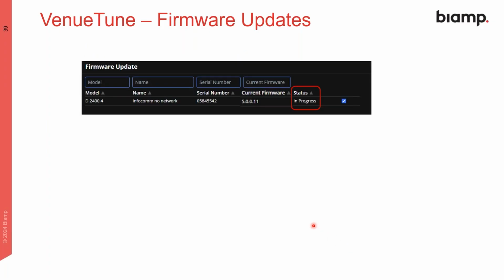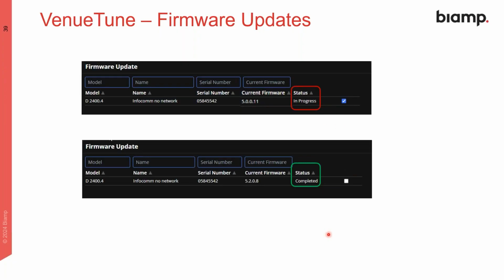Status will be shown during the update process. So in progress, and then after about 5 minutes, which is what I timed it out as, completed, and it will then show you the current firmware residing on that loudspeaker controller.